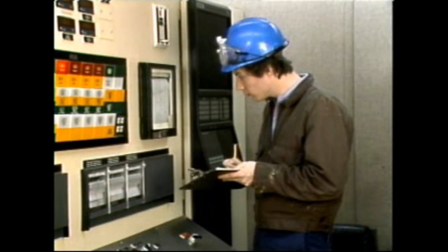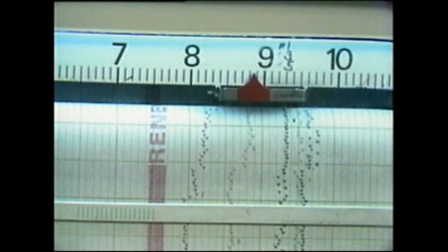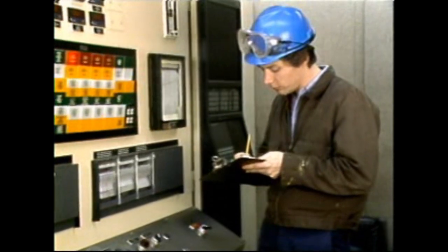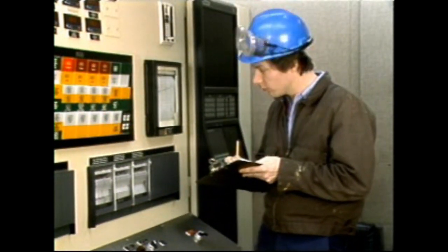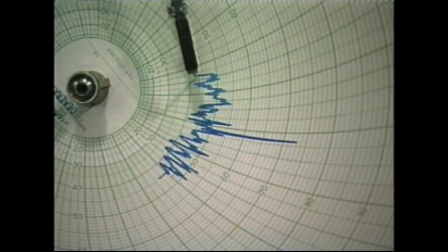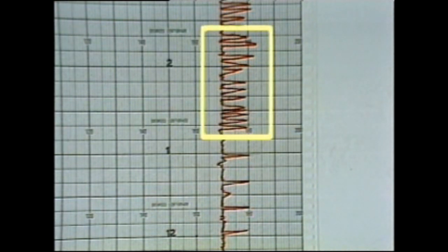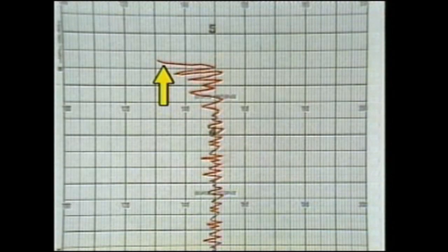The basic reference point for trend detection is normal operation. It's important that you first become familiar with normal equipment operation, normal instrument readings, and what normal operations look like on charts and graphs. If you're familiar with the normal operating conditions, you're less likely to mistake a natural fluctuation for a trend. A natural fluctuation returns to normal in time. However, in some cases, a change in the frequency of fluctuations or a fluctuation that continues until it approaches or reaches a limit could be considered a trend.